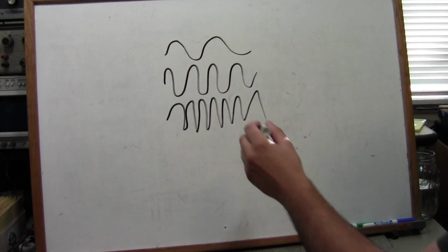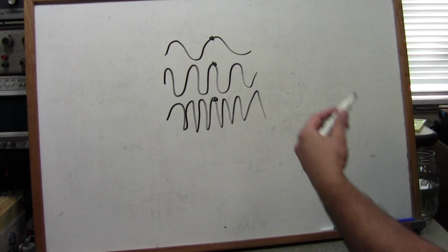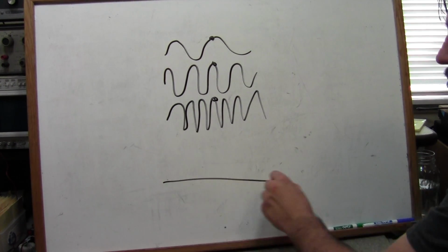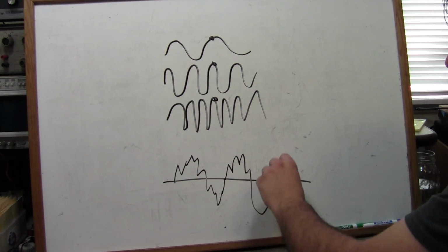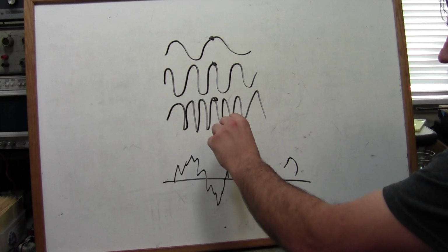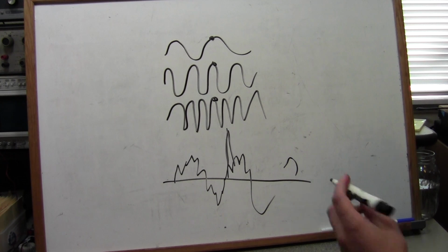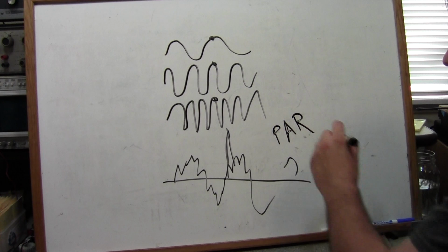Which means that at some moment, when you're unlucky, all of your carriers can happen to be positive or negative, and the output, which is going to be a mixture of all of them, suddenly for that one moment happens to go to an unbelievably high value compared to the rest of it. And this hurts what's called the peak to average ratio.